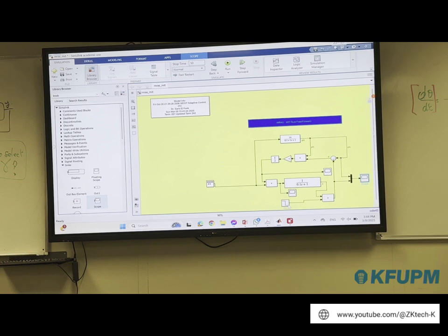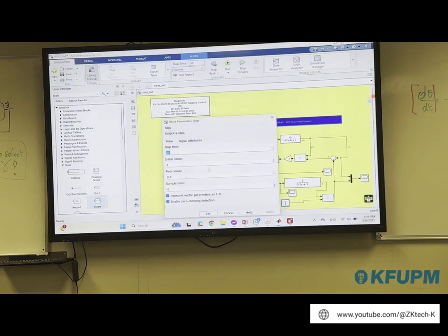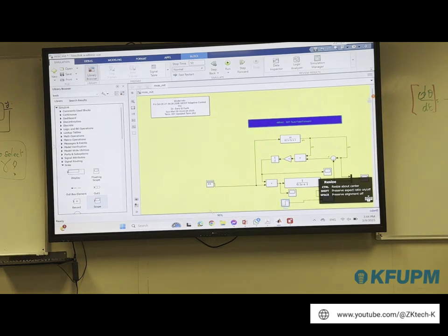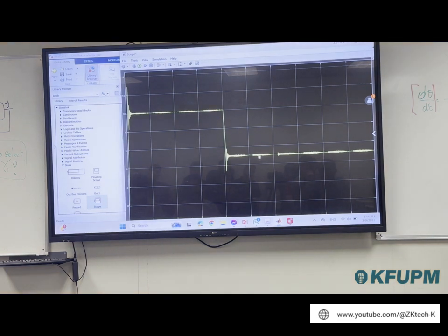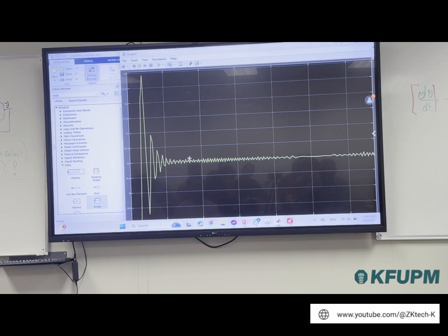So if somebody tells me the gain after maybe another, let's say we increase it, after 20 seconds we go to 2, we are expecting the value of theta to go down. So theta was up and then it goes down. Everybody's okay? Yes. You see the oscillation that we have here? It was not there before. But now we are seeing oscillation because we are using high gains on the system.